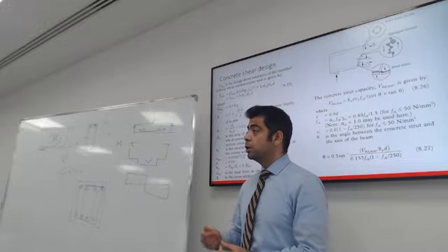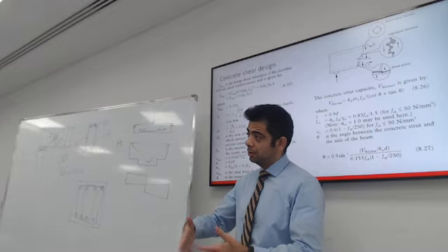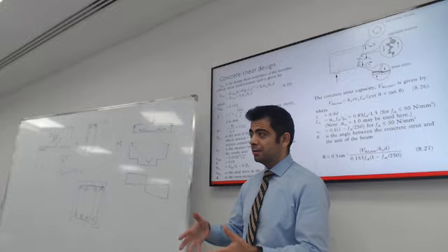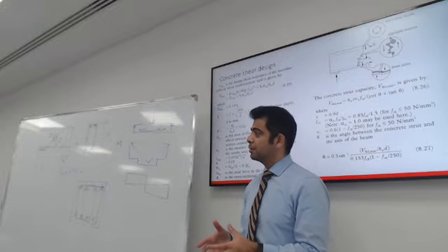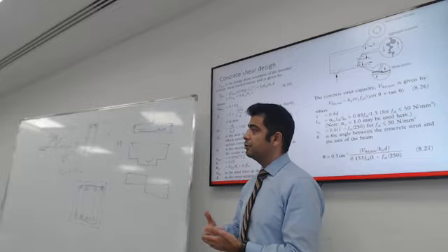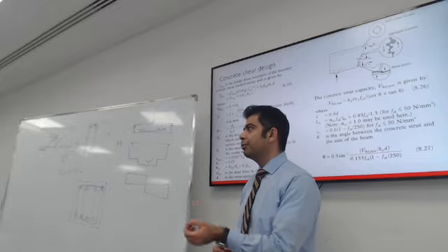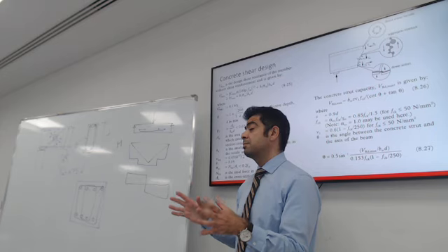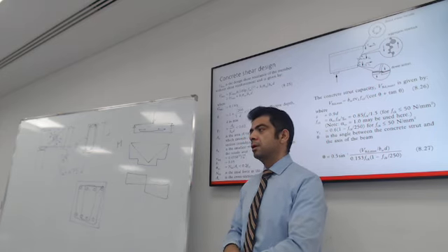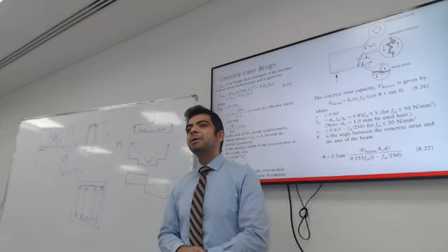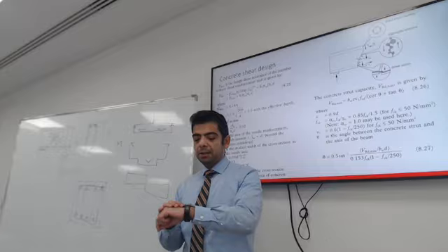Yeah. When you design the section for flexure, you make sure that the area of steel is within a reasonable amount. If it turns out that you need to add more, make sure that you don't exceed the maximum reinforcement ratio. These are good questions, and it will make sense when we do an example.